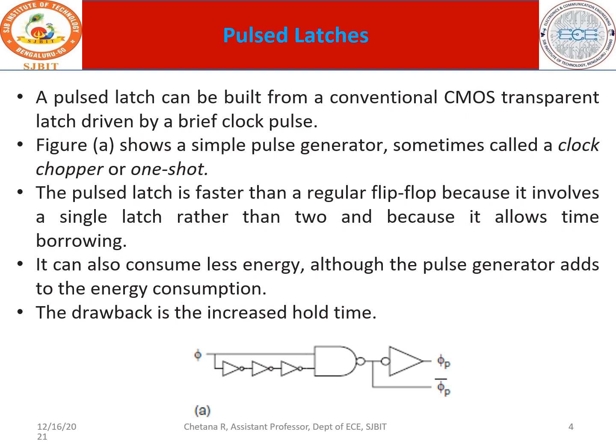This is faster than the regular flip-flop because it has a single latch only. Earlier there were two latches, but since there is only one latch here, it is faster than the flip-flop. Apart from that, this also consumes less energy, although the pulse generator adds to the energy consumption.